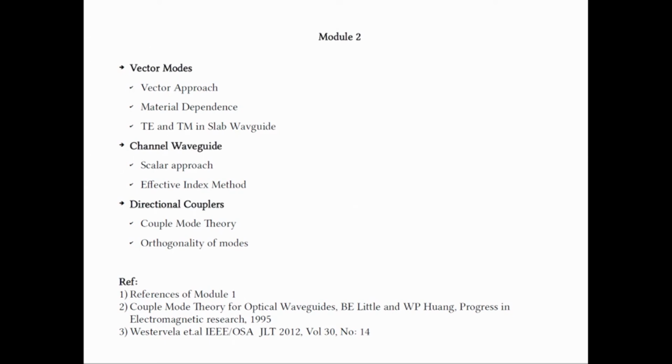One of the most important properties and striking results is that the power launched into one of the waveguides can be exchanged with the other waveguide even though there is a small gap in between the waveguides. The phenomenon is observed to be periodic, and we can periodically couple back and forth between the different waveguides. We can take an appropriate length so that you get the required amount of power coupling from one waveguide to the other. We have considered what is called the coupled mode theory to study this process, where the mode field is considered as a superposition of the modes of the individual waveguides.